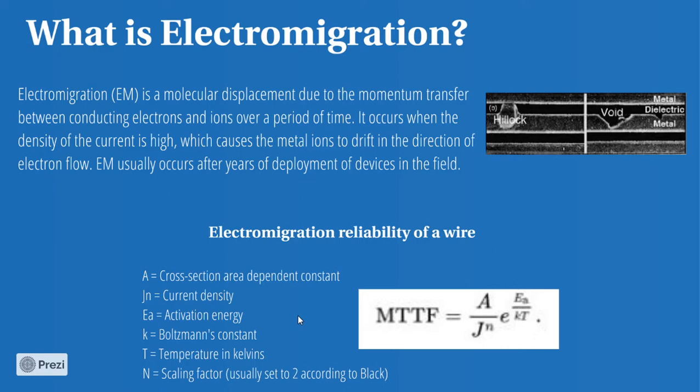Due to electromigration effects, the metal wires might burn into opens and shorts, and can increase wire resistance, which can cause a voltage drop resulting in device slowdown. It can also cause permanent failure in circuits due to shorts or opens, thus creating a positive feedback loop with temperature.